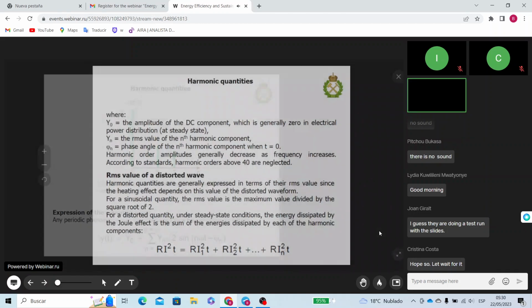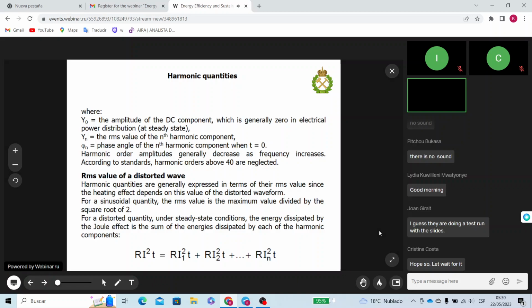And in a common situation, we may have some DC component in our spectrum, whose frequency is equal to 0. And the other components are harmonic components. Number one reflects the fundamental component. All other components are called high harmonics or simply harmonics. In all standards, in Russian national standards, in international standards, we consider the whole spectrum of harmonics up to the 40th order.